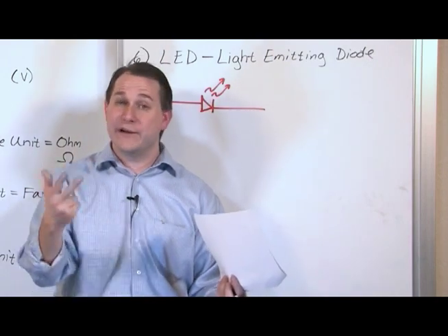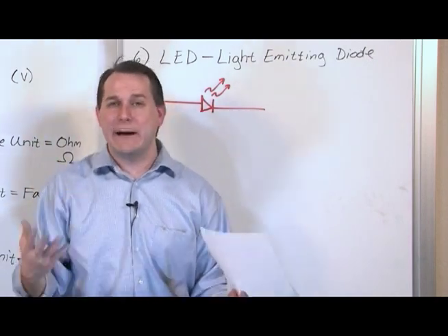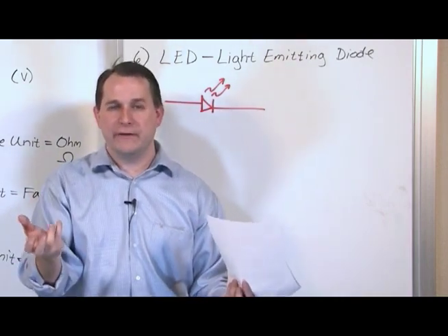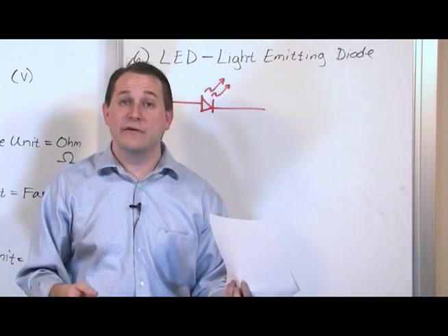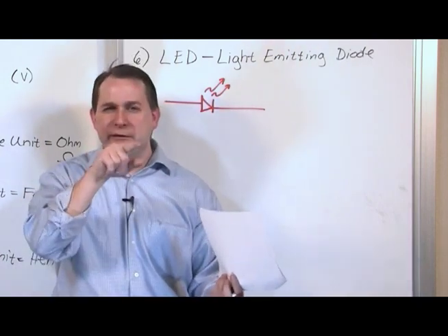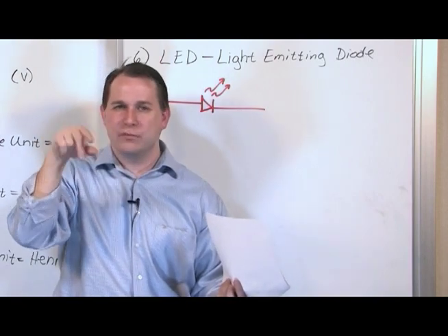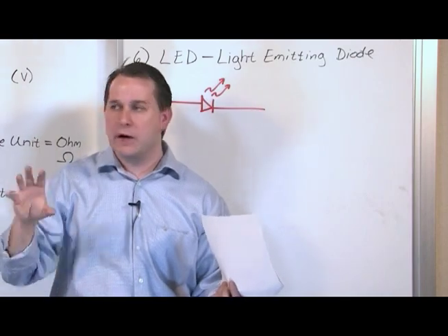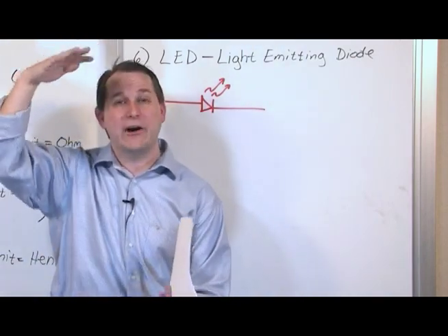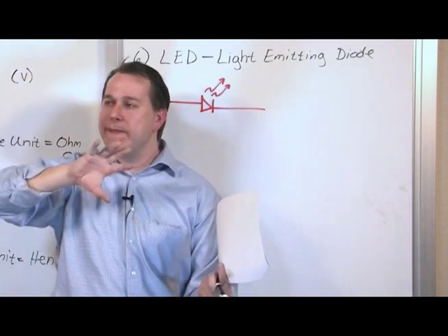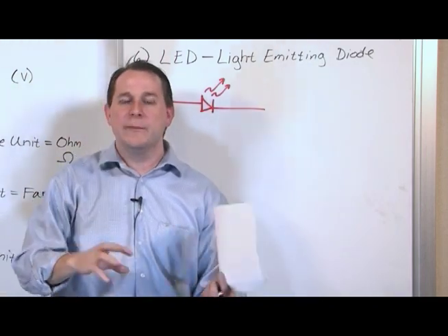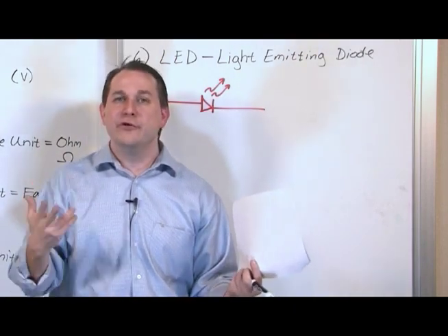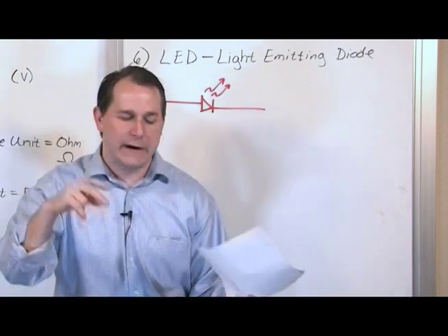A transistor's second function is that it can act as an amplifier. So when you turn the volume knob on your stereo system, you're basically manipulating those transistors in there to push out more current. A transistor can take a teeny tiny input signal, like your voice, maybe coming in on a wire, and it can make a direct replica of it on the output, but much bigger, much higher volume level, for lack of a better word. And that goes into your speakers, so when you adjust your volume, you get a nice, rich, beautiful, loud sound. That's a direct result of a transistor, right? So two functions of a transistor: switch and amplifier.